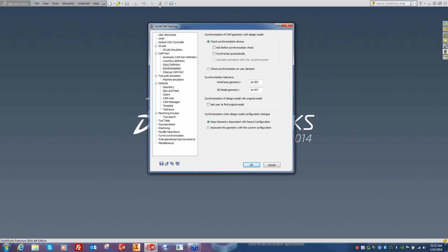Now, I like to do that because then I can put a little check mark in the box next to the toolpath, and I can see what the old toolpath looked like before I decide to let it update. Because that icon's over everything that needs to be updated, I can simply go to that element, right-click, synchronize, and recalculate, and it automatically updates my toolpath. So it requires an extra click on my side, but I also get to see what the old toolpath was and exactly what has changed over the model.